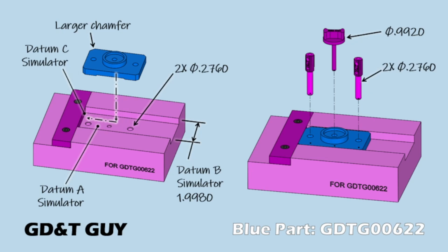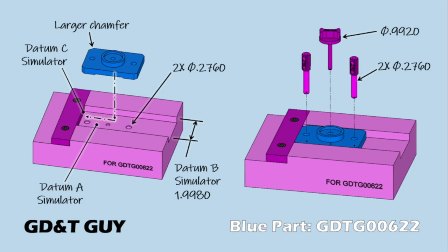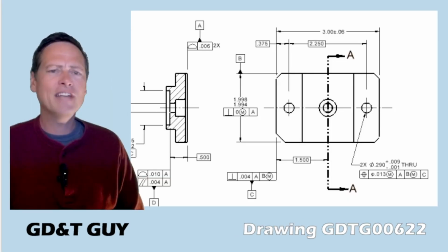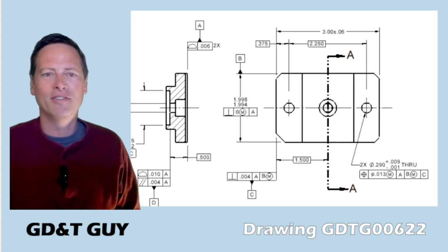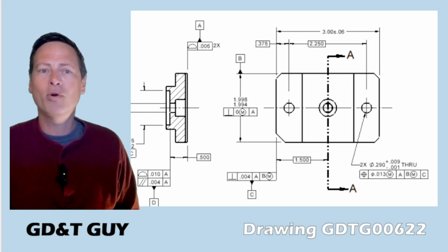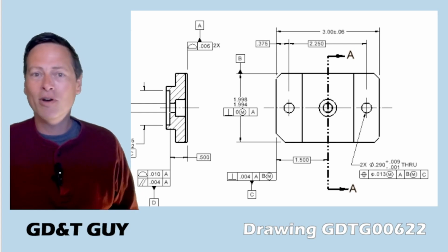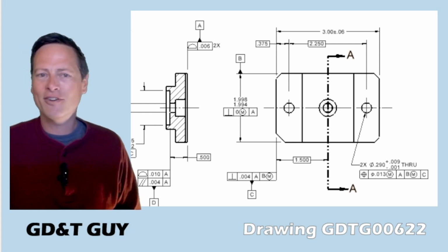The main problem with this is that if we look at the graphic on the right, the leftmost hole is located very precisely, actually excessively precisely, to the edge, which is our datum C feature. The holes are located with that same precision to each other. That's great. We need that. But then the rightmost end is not located very well at all, as relates to the hole on the right. And that's just because of the way everything is stacked off of the leftmost end, which we're saying is an important datum feature. And the rightmost end is a throwaway, a loose tolerance clearance feature.